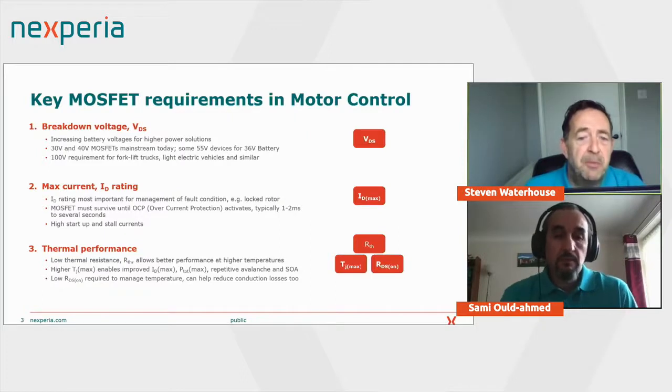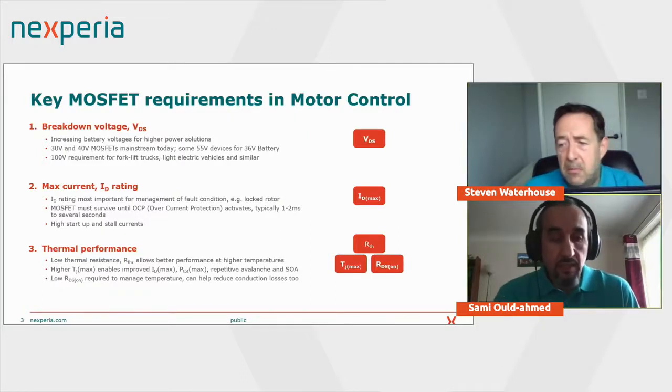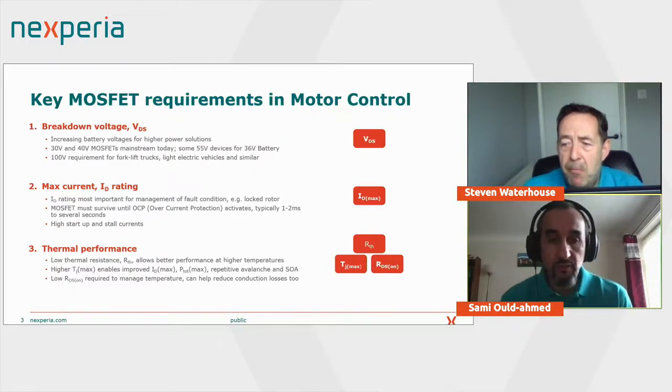If I may add to that, there are motor control circuits that require big capacitance in the drive itself. And the MOSFET used to enable that circuit needs to cater for the huge inrush current demanded by the capacitors, which can be quite significant. Therefore you might want to consider a soft start for that circuit, and therefore linear mode, which then results in the MOSFET requiring a strong SOA.